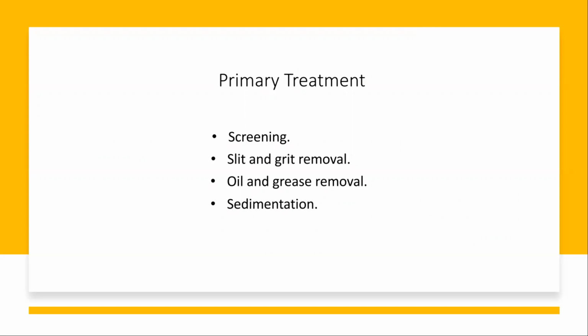Then the next step is silt and grit removal. The sewage is passed through channels in a grit chamber very slowly. The silt and grit particles such as sand, pebbles, broken glass, etc., which are heavy, settle down at the bottom of the chamber.